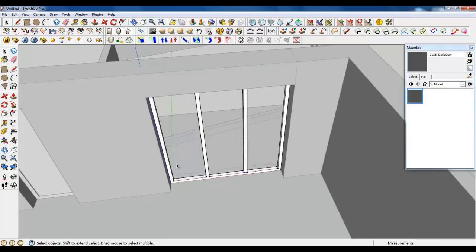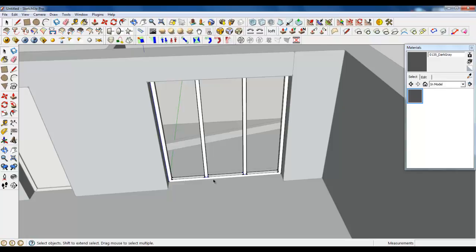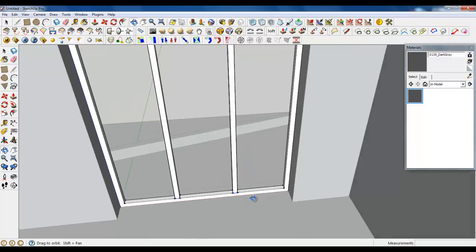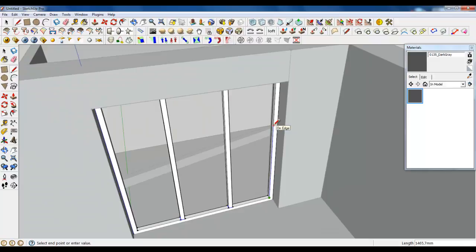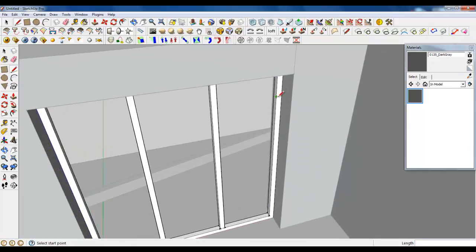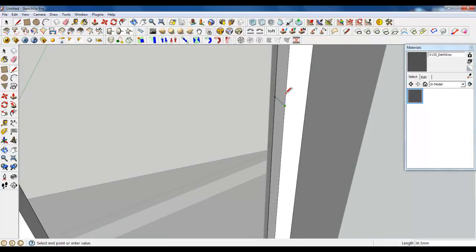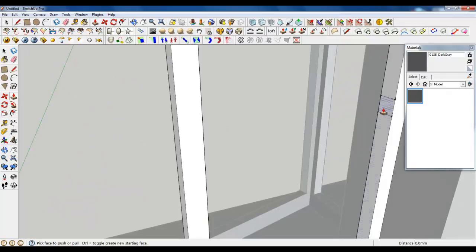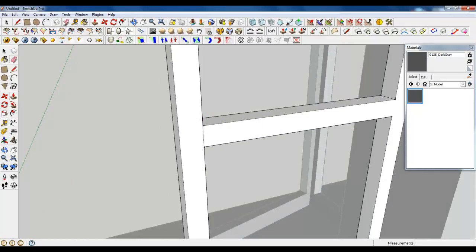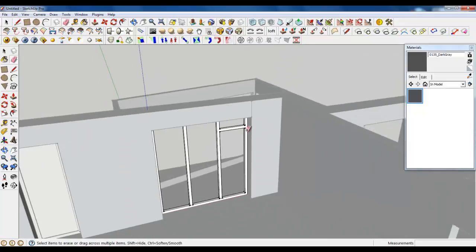Now let's create one window there, and there would be a door, but the door is always about 2 meters high. So type in 1.9 meter and create, let's type in 16 also, and make this thing a small window and a place for the door.